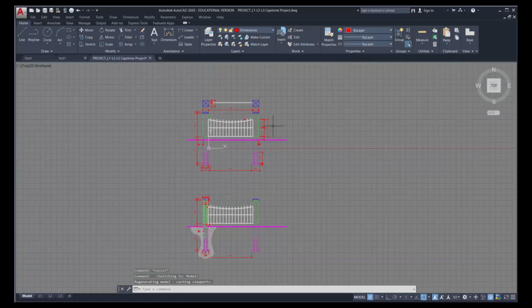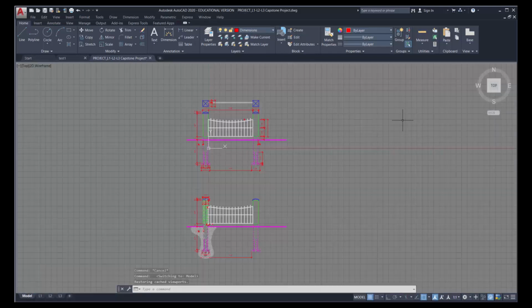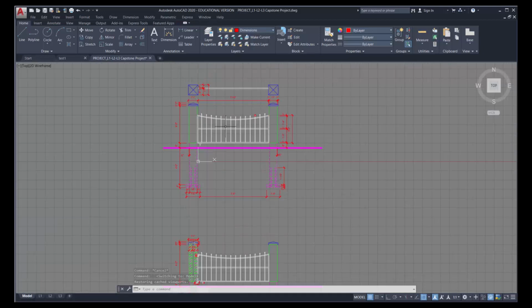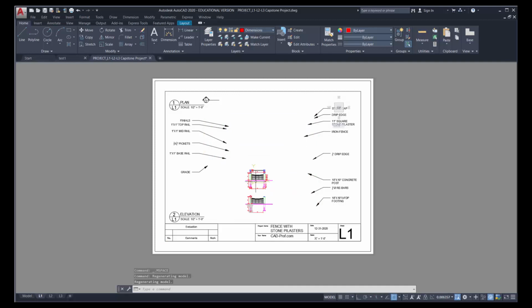And one of the things we're going to learn is how we draw in CAD in a single file format. So all of those drawings that you saw were basically a single file, but what we do in CAD is we create windows. So we've been working in model space for the drawing that we did earlier today, and that's what these are. They're drawn in model space, but we're going to be learning how to work with paper space. Paper space is the terminology that we use for the printed area. This is a page that's ready to go to print, and we actually open up a viewport to see the model within our printable page.